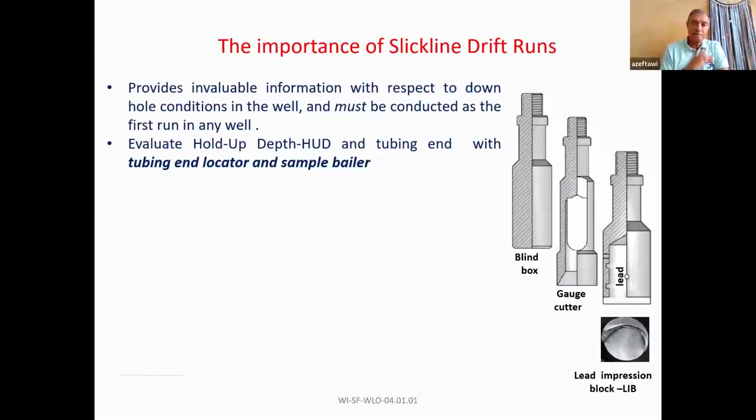So please treat an artificial lift well as a live well. People will say, how? If we stop the pump, pressure will go to 0. I said, yes, but not immediately. It might take 15, 20 minutes. So you are dealing with a live well, but dealing with it as a dead well? No way. So yes, please deal with artificial lift wells like live wells regarding pressure rating and pressure testing. Whether it's alive by itself or live because of something helping it, like artificial lift.